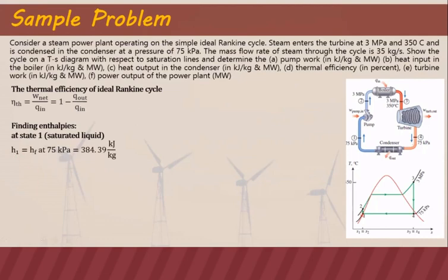The enthalpy at state 1 is just hf, the enthalpy of the liquid at 75 kilopascal, because the pressure here is 75 kPa.